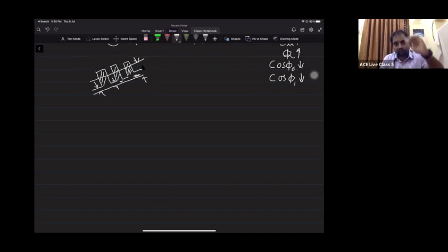It is something like in your power system, you might have discussed something about corona. Corona is not the pandemic which I'm talking about. What is a corona? If you take a conductor, then under foul conditions, when the field intensity exceeds 10 kilovolts per centimeter, the air molecules surrounding the conductor will get ionized. So the area around the conductor will act as a path for carrying current, and the current can try to flow through that path. So in this case, what is the effective area of the conductor? It increases. The true area is small, but the effective area will try to increase.